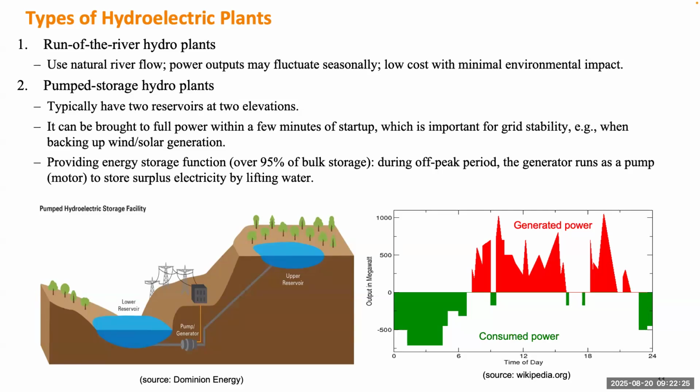If you can keep the balance and treat the power plant together with neighboring systems as a microgrid, or a smaller system, the total energy can be balanced. The red color, the peak hours, is like discharging this energy storage, and the green color means charging this energy storage.